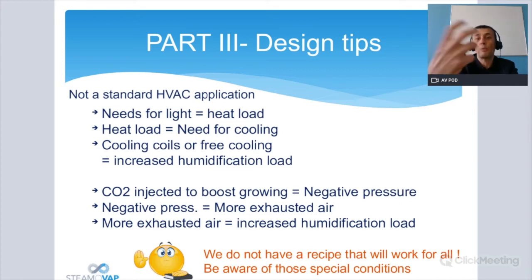So you need to exhaust more air to make sure that the CO2 will not go elsewhere, because it can be harmful for human beings. So you don't want to lose the CO2 either. And then when you exhaust more air, you increase the humidification load again. So you have to ask all these questions to the engineer that will be in charge of designing a room if you have to work with such a project.